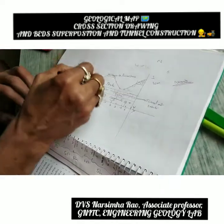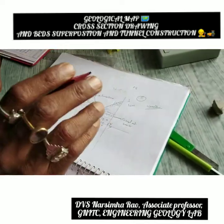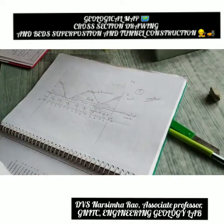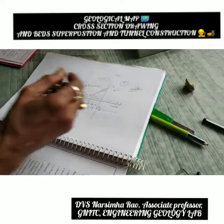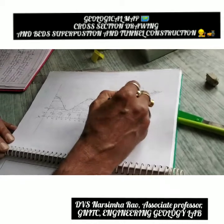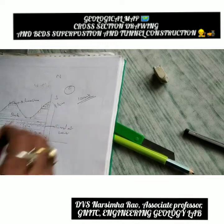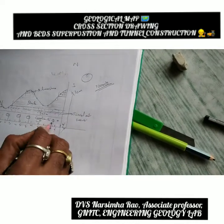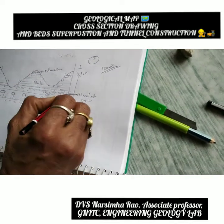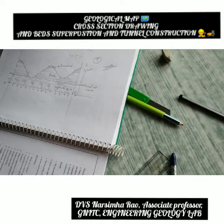Now, a dam is proposed at the eastern side and they want to construct a tunnel like this. Now this is clear. Now this you have to draw, and now what is the result? Now when you see the order of superposition, the first bed is formed here. So from lower to the upper: conglomerate, sandstone, shale and limestone. Now sandstone is the feasible rock for the construction of tunnel because sandstone is somewhat porous and permeable.